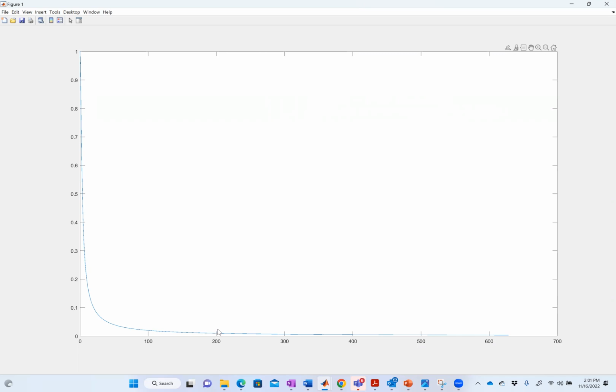If I place it there, then that ripple, that variation, that sine wave that I have at the fundamental frequency and the speed will be tiny, right? It'll be 1% of the average, right? That's how we apply this.